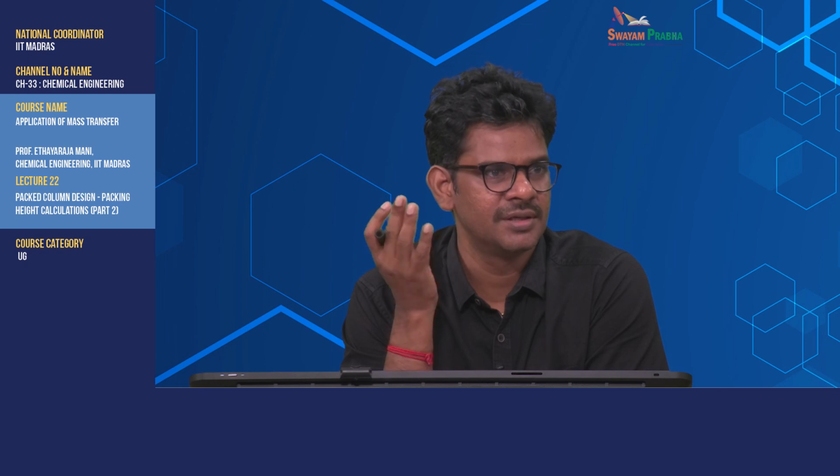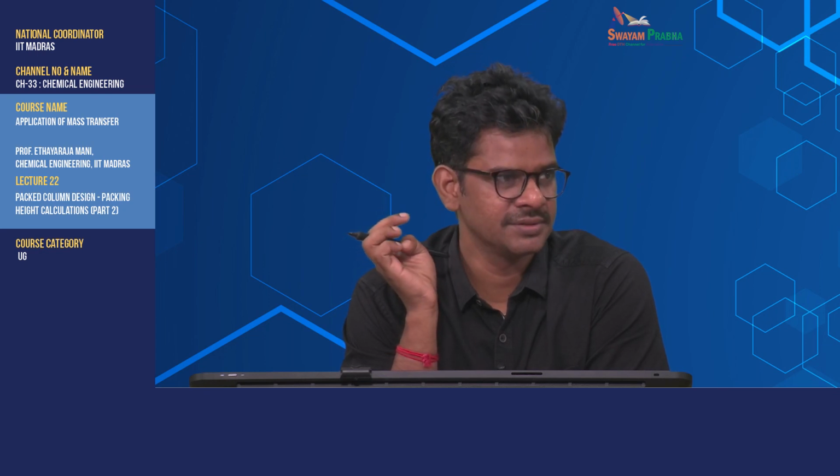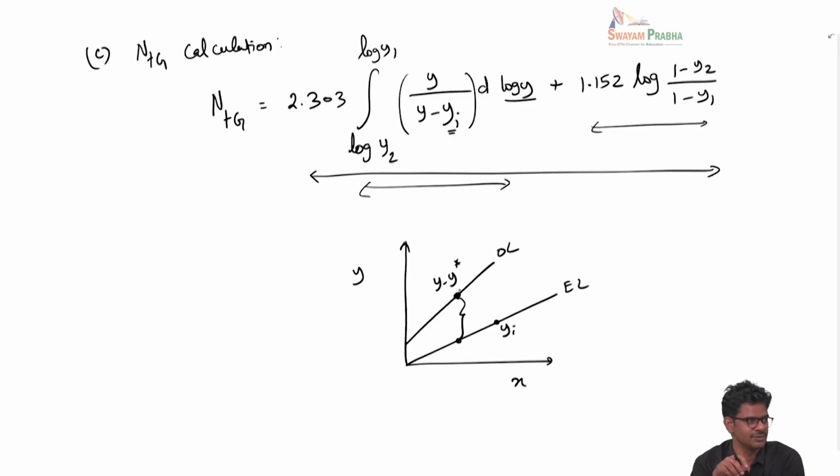Driving force line. So it depends on the ratios of the mass transfer coefficients kx, ky. That is only for the dilute limit, but here we are using the concentrated limit. So we need to find an equation for the driving force lines. Okay, there will be several such lines. This need not be a straight line, by the way. Okay, for every y on the operating line, there will be a corresponding driving force line that will reach the equilibrium line, and from there you are going to read the interfacial concentration yi. Okay.